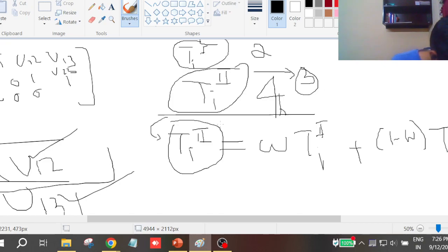Under relaxation parameter is used to accelerate the solution. No, over relaxation is used to accelerate the solution. To reduce the memory required per iteration. No, it doesn't reduce any memory. I don't think so. Select proper method to solve the equations. I don't think so. So I think D should be the answer.